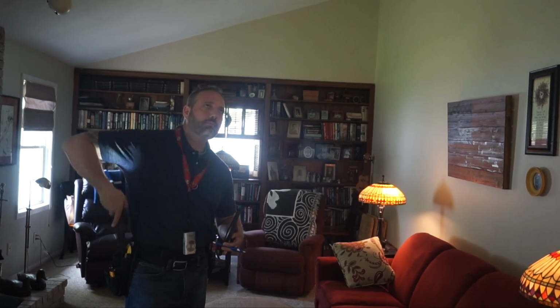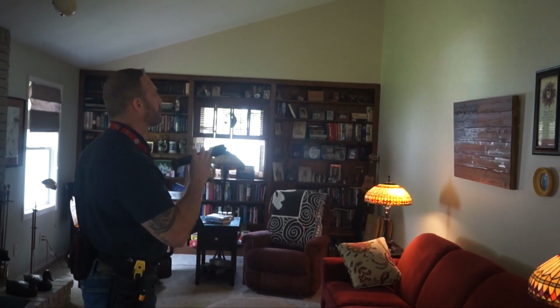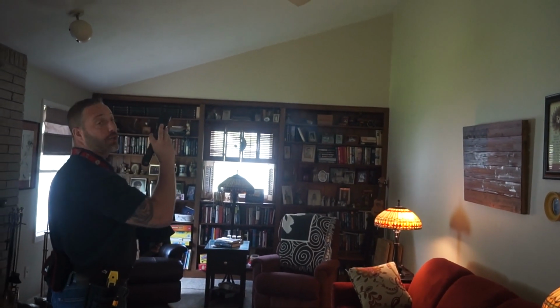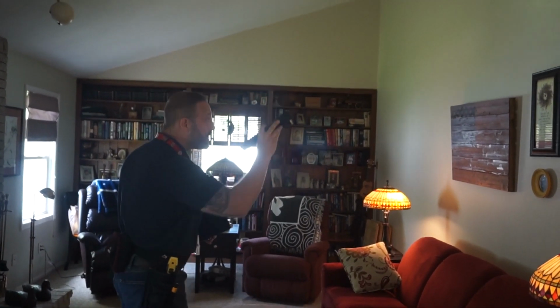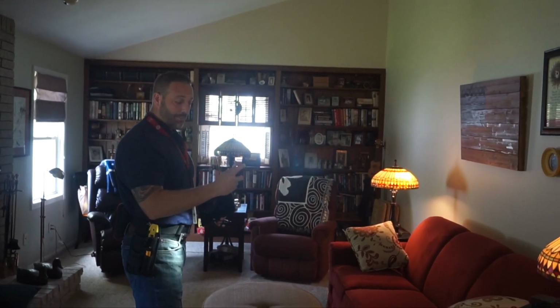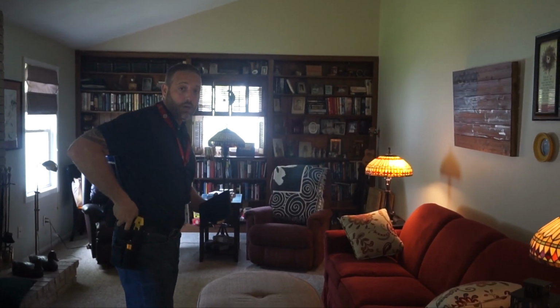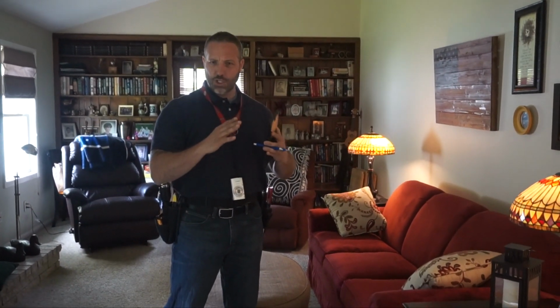All right? Now, when it comes to those cracks, we're trying to see if they're continuous. We're seeing if there's a crack along the ceiling and then along the wall, because that's an indication of a continuous defect. Sometimes you may have cracks between the sheetrock, or maybe expansion and contraction or uplifting of the trusses. Again, that's more of a cosmetic defect.